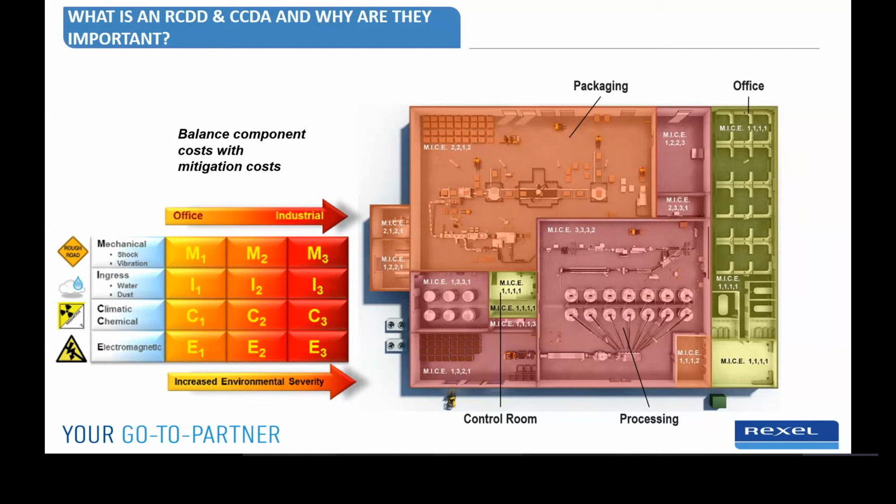They take more into account the logical aspect of the network. So things like the IP addressing scheme across the system. If you have different areas that are in different networks, how the routing happens between those. If you need redundancy, what redundancy protocols are going to be best suited for that environment, and then things like wireless. If you wanted to implement wireless across your plant floor to allow for things like tablet mobility, they'll take into account how logically those requirements play into the network design.